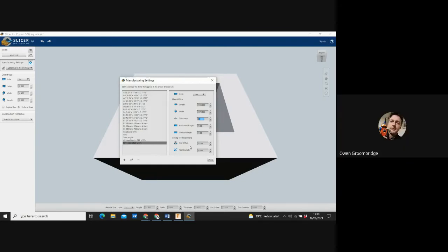Yeah, I was going to say, in terms of larger scale objects, if you're, say, machining 18 mil plywood, for example, offset's really, really important. In terms of laser cutting, with 4 mil ply, it's not so important as such, because at the end of the day, you have to bear in mind that the beam of the laser has a diameter, so there you have an offset there.